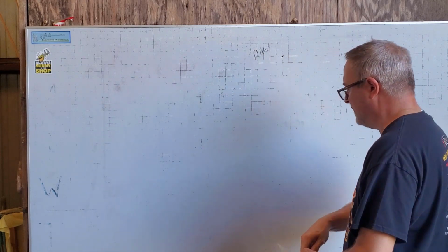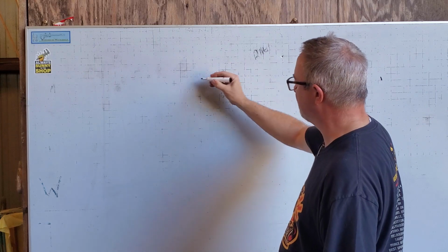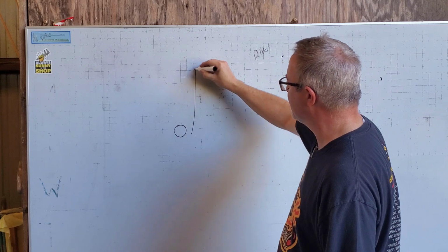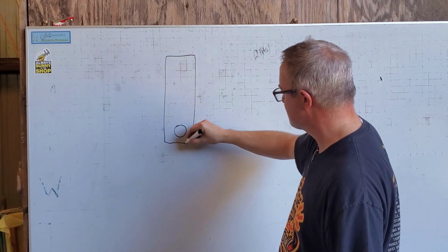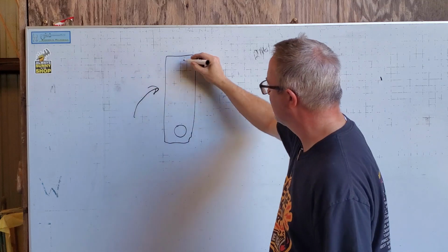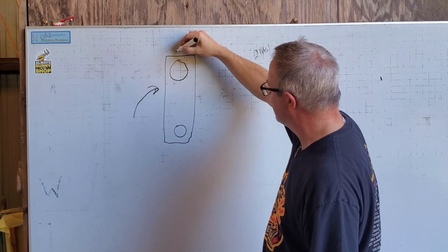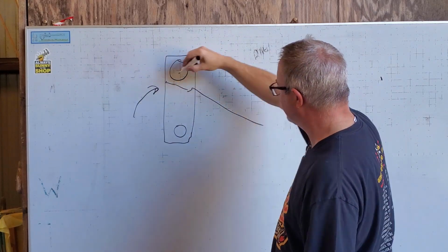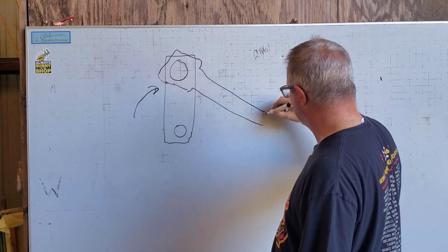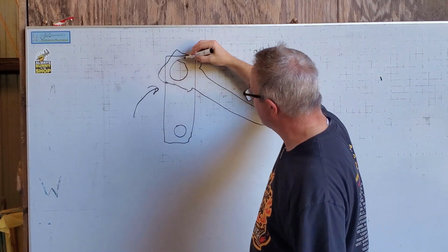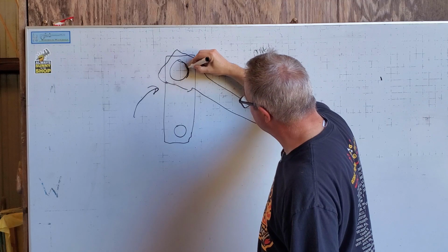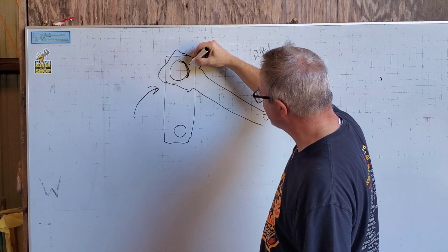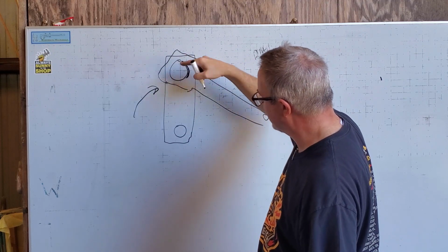Because when you have a crank pin, and let's say the crankshaft is at 90 degrees, and we're coming up like this. So we've got a crank pin here that until this point has been pushing and accelerating the connecting rod and the piston. So it's loading the front side of the bearing. It's squeezing the oil between the bearing shell on the connecting rod and the crank pin.